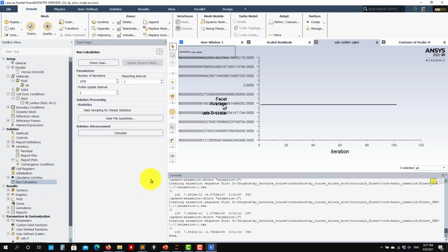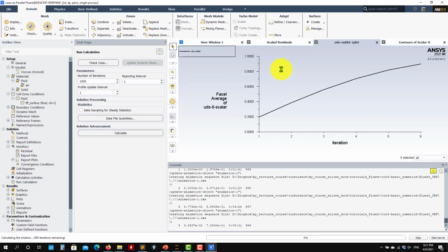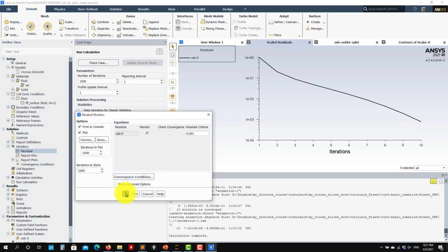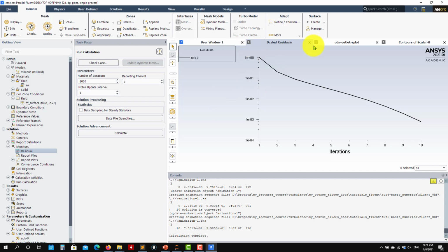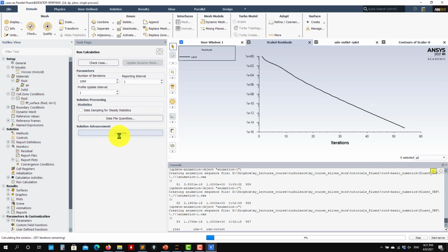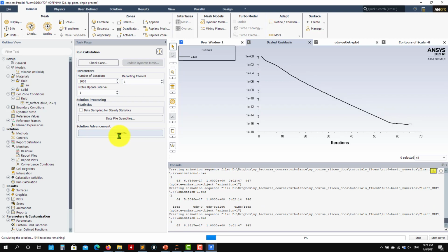And if I run, everything is okay, I reach convergence. And if I disable this convergence, just to show you, and let it run for a large number of iterations, this is something interesting. See how your residuals are going down. This is a clear indication of a steady solution, but see what is happening there. Now those residuals start to flatten.